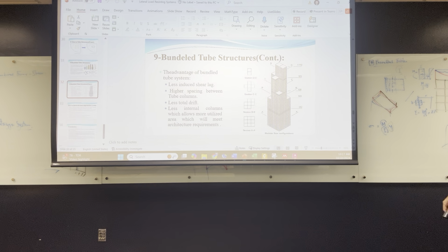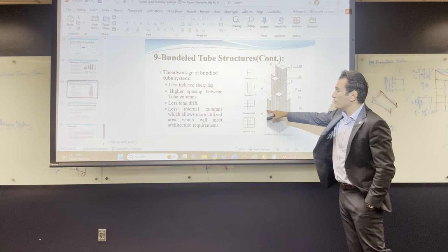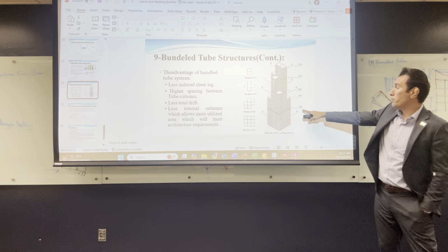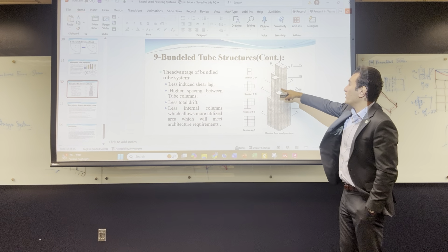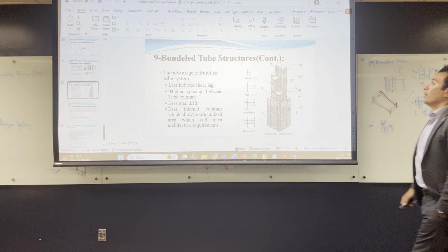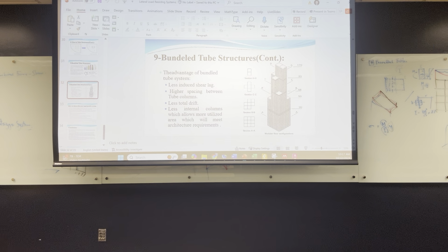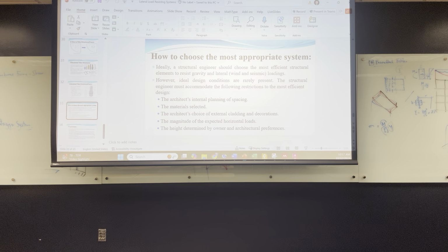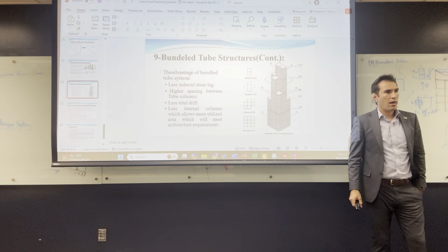So that's for the Sears Tower, and this is how the tower actually looks. They make a belt around it, and maybe there's an outrigger inside as well. There's one here, and one over there, to enhance the tube action between the bundled tube system. Is that usually where they have living space or just mechanical space?